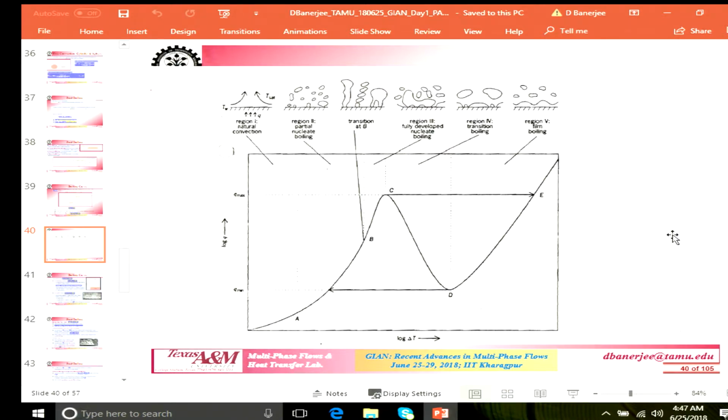But if you chill the liquid, if you subcool it, those contacts go away. So, in saturated film boiling, even if you are pretty high up over here, there are periodic liquid solid contacts that occur, and your conventional film boiling models do not really account for that phenomenon. The conventional models for film boiling, Berenson's model for example, work very well when it comes to subcooled boiling. But when it comes to saturated boiling, Berenson's model does not account for this phenomenon, the periodic liquid solid contacts.